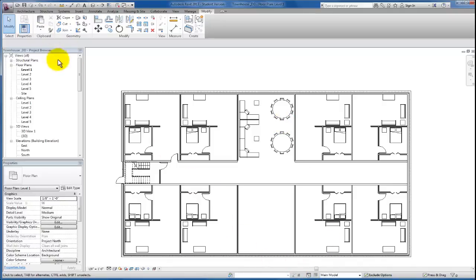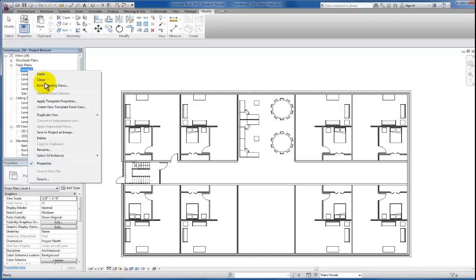The last thing I want us to do is to just go ahead and set up a partial plan where we can show that second option, realizing that many times when you lay out your plans, we'll create a partial plan that might show that alternative secondary layout. So we're actually going to start from our level 1 plan, and let's just go ahead and duplicate this view.